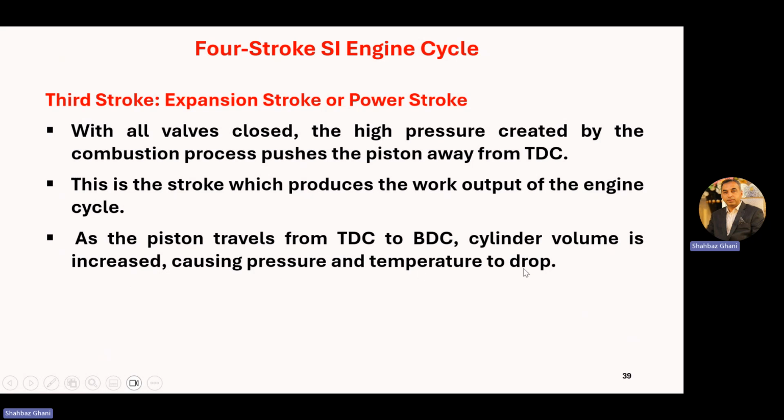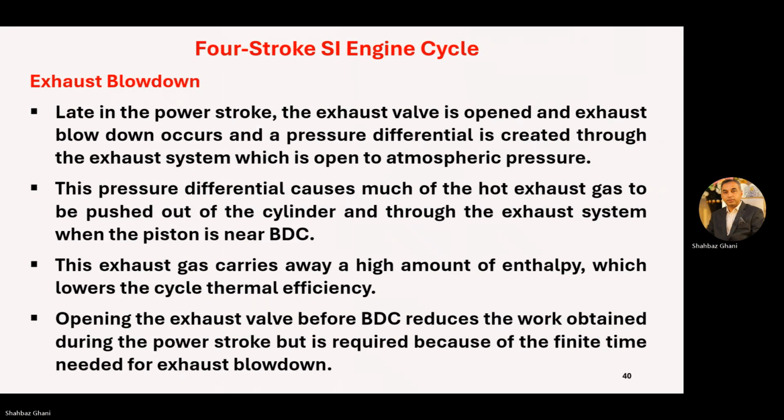So the piston is moving from TDC to BDC. The volume is increasing. When volume is increasing, it is getting more area. When getting more area, your pressure is dropping, your temperature is dropping inside the cylinder. Now, exhaust blowdown, another important phenomenon.